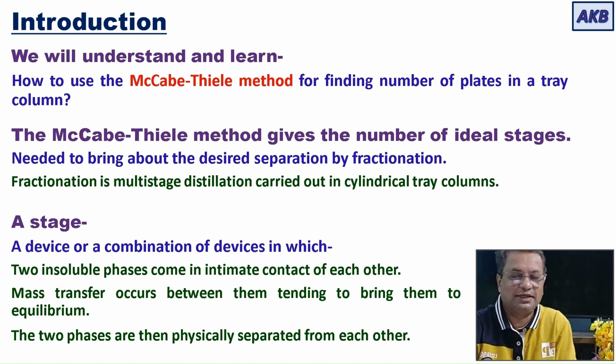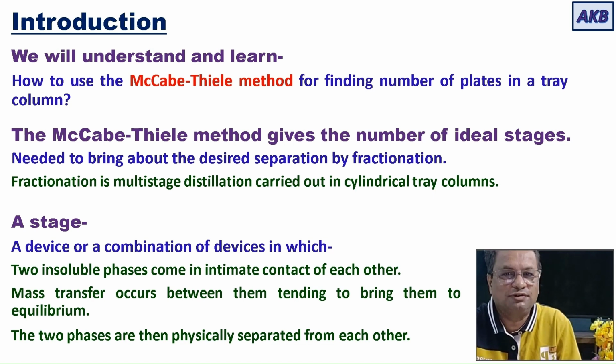Are you understanding it? So a stage is a device or a combination of devices in which two insoluble phases come in intimate contact with each other. Mass transfer occurs between them, tending to bring them to equilibrium. And finally, they are physically separated from each other. So that constitutes a stage.